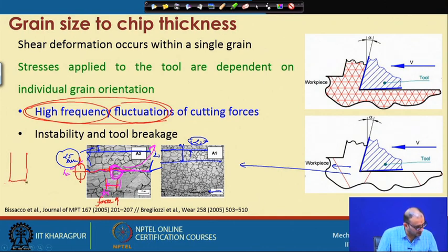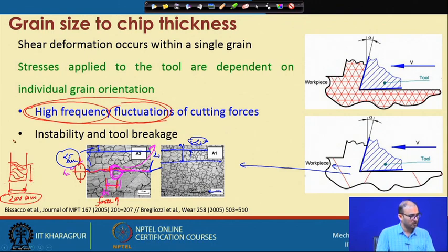So this is our end mill cutter, and consider this diameter to be 200 micron. Now when the tool diameter is very small, the effective cutting length is also very small, because you cannot have a very long overhang on this part. Now when you are cutting this part, consider it is moving in this direction, and you are getting one particular boundary here.